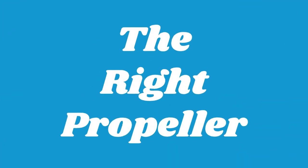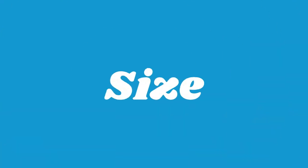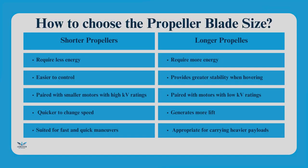Choosing the right propeller. Choosing the right propeller is crucial. Here are the key factors to consider. Size. Propeller size is measured in inches and describes the diameter of the circle the blades make as they rotate. Shorter propellers require less energy, are easier to control, and are paired with smaller motors with high kV ratings. They are quicker to change speed, suited for fast and quick maneuvers.